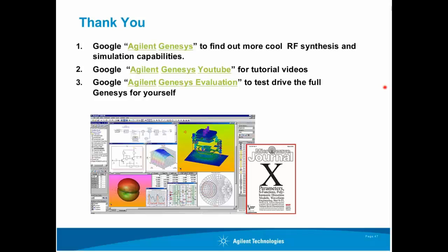Hey, thanks. A question from Dan. How can you choose different input and output impedances for the filters when the impedances are different from each other? Well, that was on the specifications tab back a little ways. There, on the specification tab, there is input impedance and output impedance, and you can select those individually.